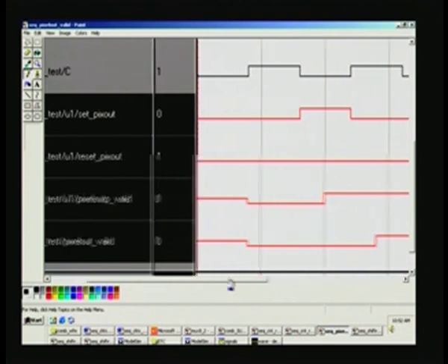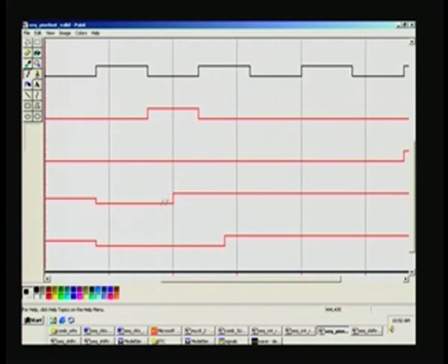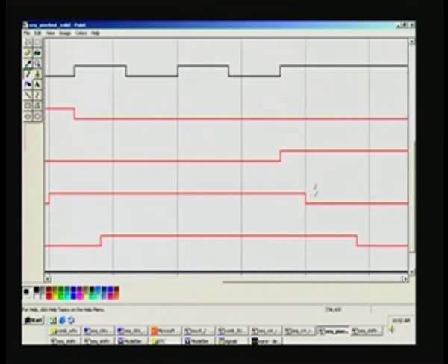And coming to this here, the last 2 are pixel out, and so you see here pixel out P is here, and this is staggered by 1 clock pulse, and when it goes low, this also follows suit. So, it is nothing more than this; this is the basic logic in pipelining registers also, which we will see in more depth when we go to adders and multipliers, arithmetic expressions, how to evaluate them, compute them, and how to evolve new algorithms for that will also be seen there.